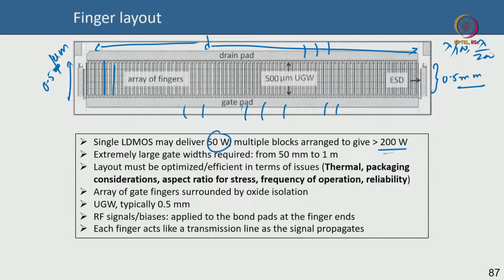it over to all this with multiple wires, because you do not want one wire to be feeding and there will be delay across as it propagates. So you want multiple wires feeding them intermittently, and these wires' length and dimension also matter a lot, by the way, of this wire bonding. But these are the issues that generally have to be tackled.